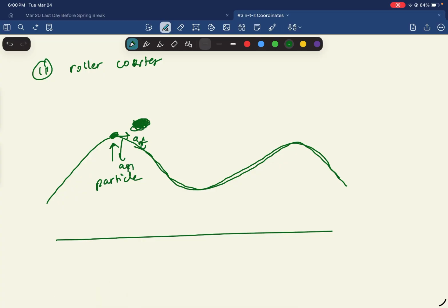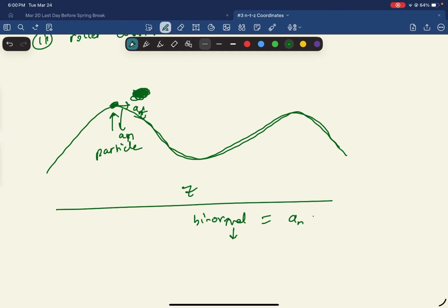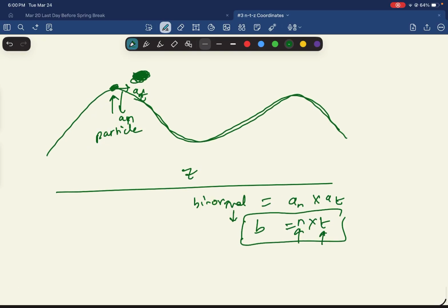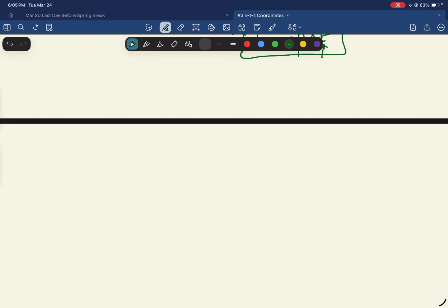And here comes the next part, the G part, which is also called binormal. The binormal is basically the cross product of the normal and the tangent directions. So the binormal is always perpendicular to both the normal and the tangent. One statement to remember: the XYZ coordinate system explains the position, while the NTG coordinate system explains the motion of the particle.